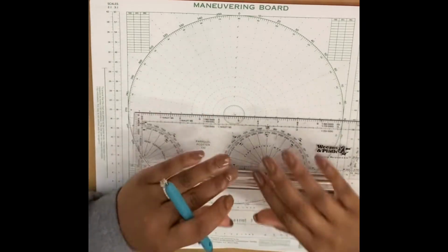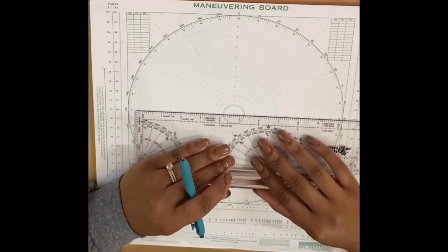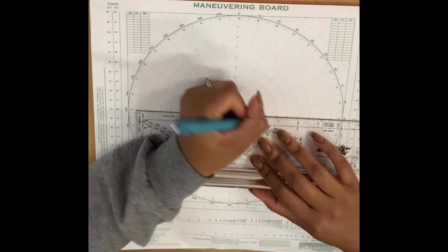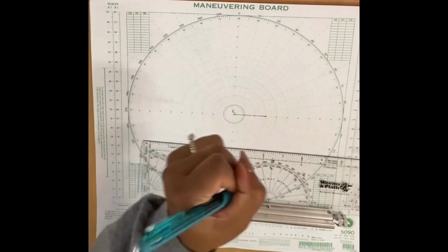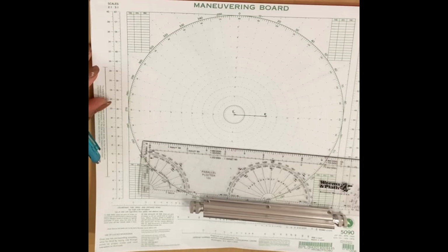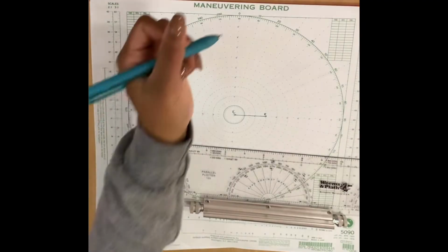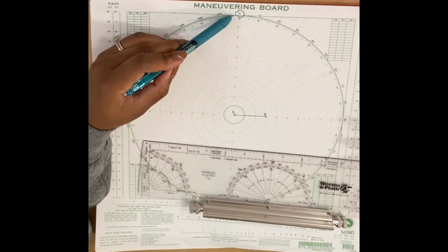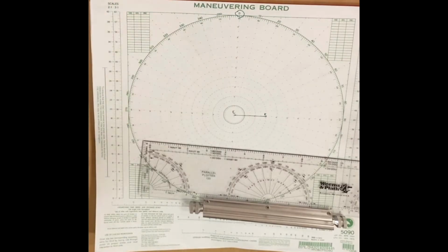So let's go ahead and plot everything that we know from the problem. We know that we are on a course of 090 at 15 knots. So we know our ER vector. We also know the bearing and range of that maneuvering ship or that contact. So looking at the numbers of 9,000 yards and 7,000 yards, I'm going to go ahead and decide to use that 1-to-1 scale. So I'm going to circle my 0 up here to remind myself throughout the duration of this problem that I am using the 1-to-1 scale.